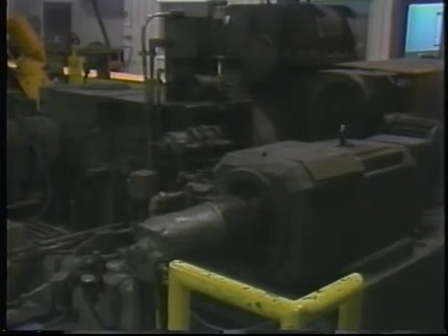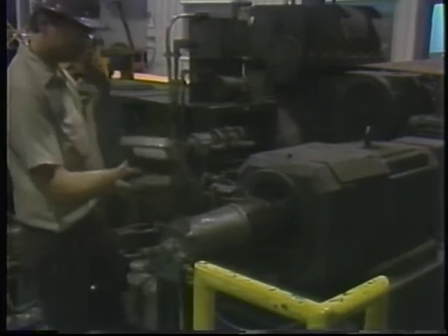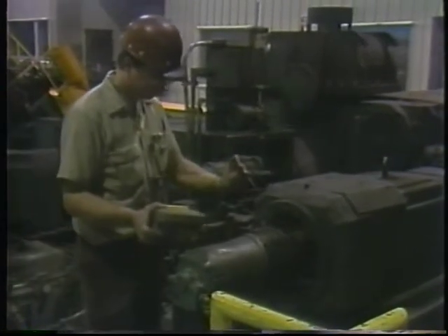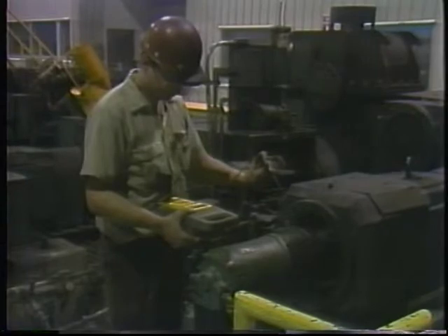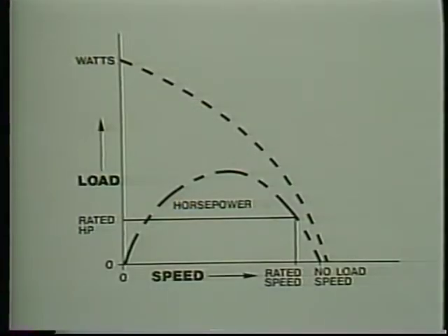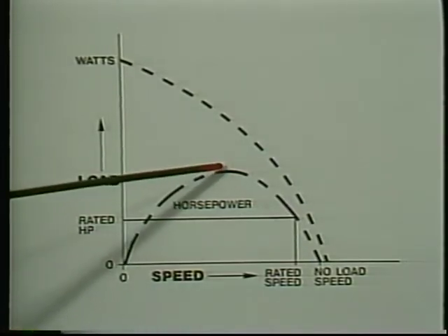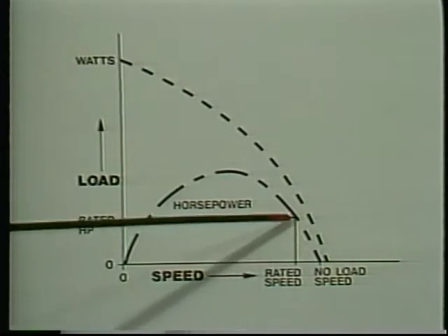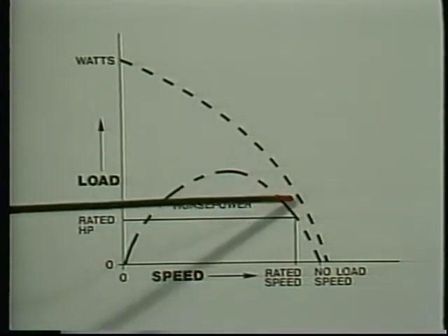Of course, anyone who works around motors knows that they get hot. They will heat up fastest at stall speed when they are consuming a lot of watts, and all those watts are converted to heat. Operating under heavy loads at low speed is almost as bad. At maximum power, the efficiency is high, but the difference between watts in and horsepower out is still large, and a motor will heat up if it is operated under these conditions for very long. At rated horsepower, a motor will heat up comparatively little.